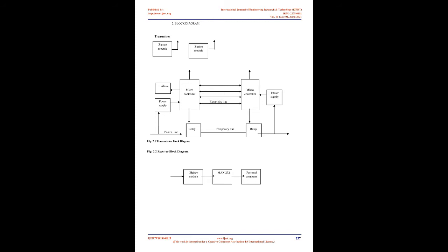3.2 Power supplies. The AC voltage, typically 220 V RMS, is connected to a transformer, which steps that AC voltage down to the level of the desired DC output. A diode rectifier then provides a full-wave rectified voltage that is initially filtered by a simple capacitor filter to produce a DC voltage. This resulting DC voltage usually has some ripple or AC voltage variation.